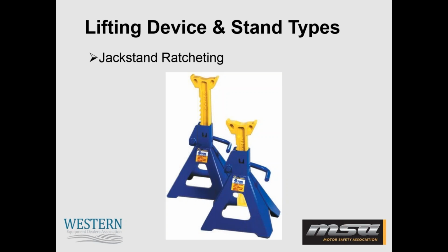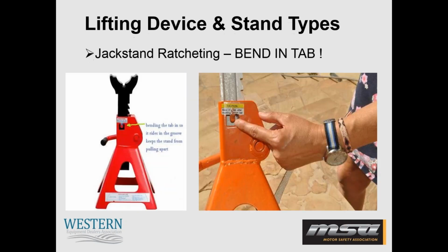Also, be aware of the handles. If these handles are not properly engaged, or if they're bumped out of position, the jack could drop down to the next lower notch. And with these type of jack stands, they are to only be used in pairs.